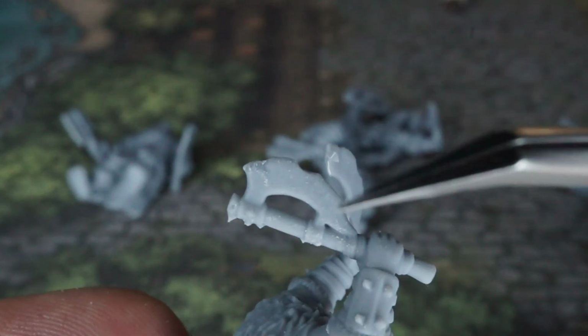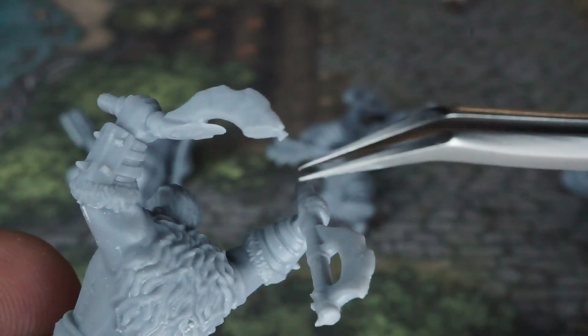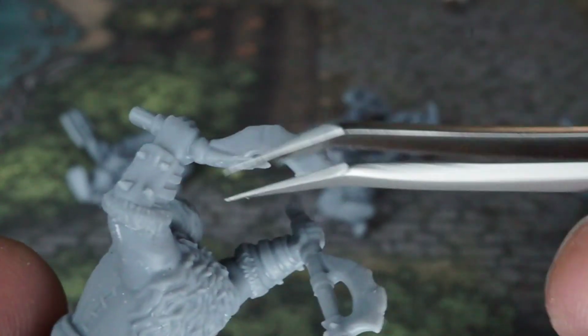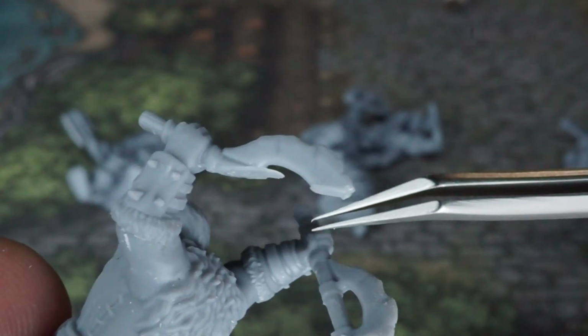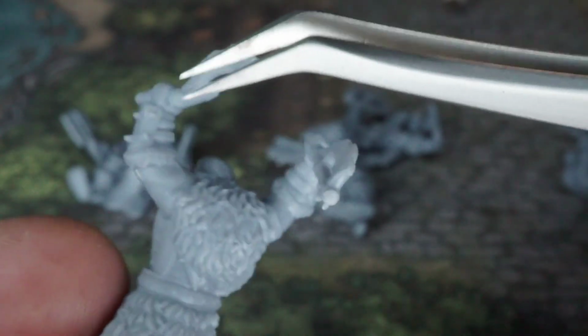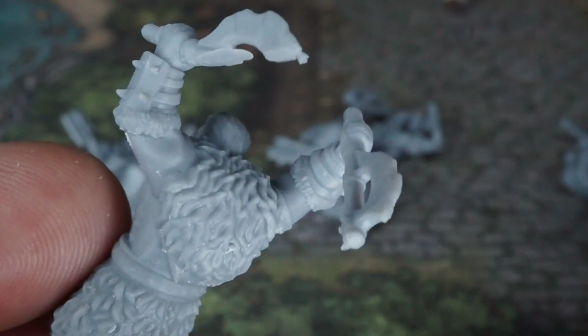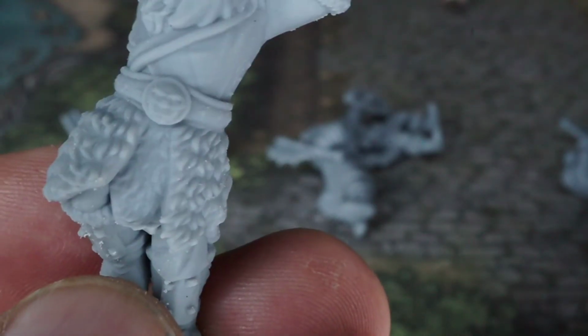And so we can see that happen in various models occasionally. Here's a great example. Here's one of his axes. Let's get it in focus here. And then here's his other axe. What happened to his axe? What happened was we just didn't get enough supports here, and we didn't get what we needed in order for the printer to pull this off the build plate, and so it just ripped the axe right off the supports and flattened out.